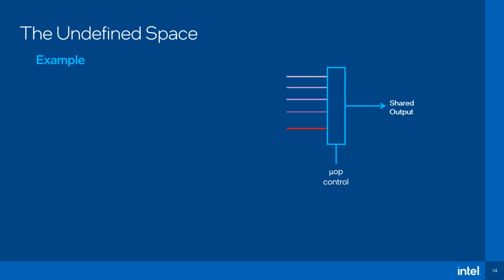Let's look at a simplified example of an output bus that is shared by many operations. One of the operations that can read it has an undefined writeback data. Let's call it UOP A, the consumer UOP. The data that will be read depends on the operation type. Each operation selects the relevant branch to read, but UOP A doesn't write any data and selects default input. So in some conditions, it could potentially read data that was left behind by a previous operation.